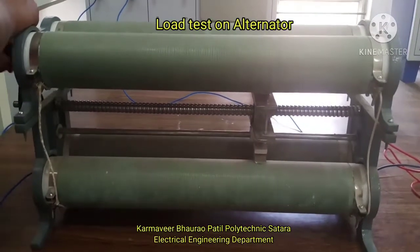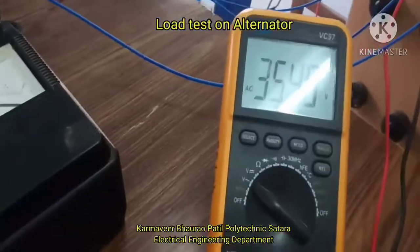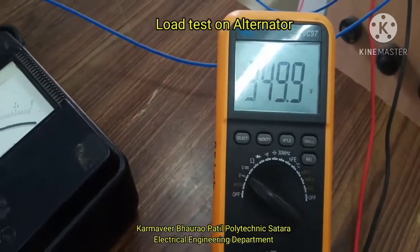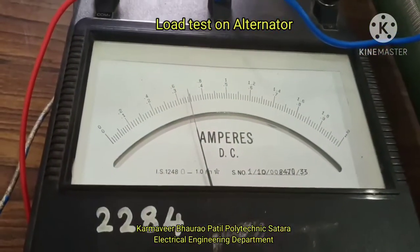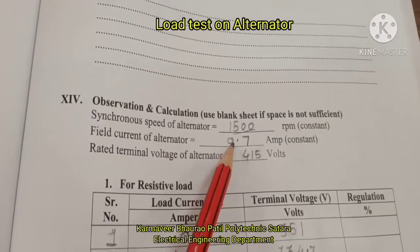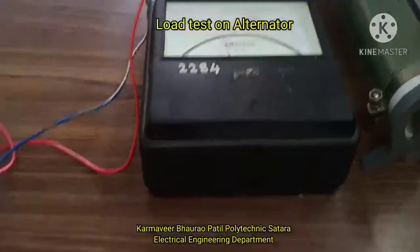The excitation voltage slightly increased, so reduce it, and it is now adjusted to 350 volts. Excitation current is 0.7 ampere. We are taking that one time, and now, with the inductive load completed, we will go for the third observation table, capacitive load.